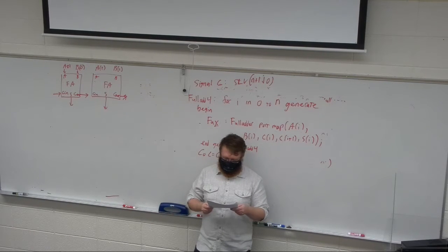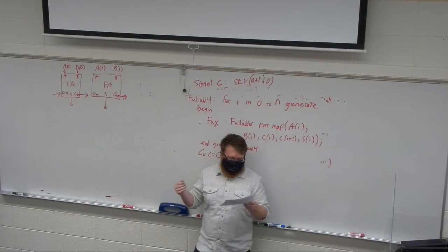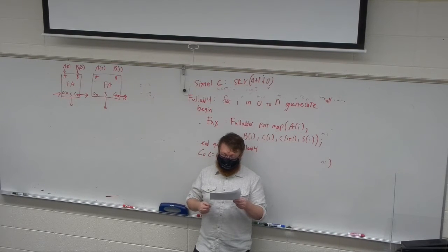Number 2, the only trick on that one is some people listed reset or clock. They don't do anything for you because it's combinational, so we don't need to reset it or clock it. The true false were mostly correct. With 3, people just, I think, flipped in their heads which one was which. 3 is the principal difference between a PLA and a PAL is that the OR array for the PAL is